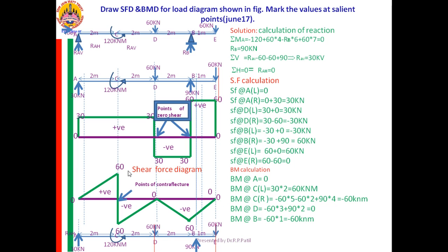So how can I define the point of contraflexure? It is a point in the bending moment diagram where SF changes its sign from positive to negative or negative to positive. That is the definition. But as for its importance, when you are designing structures in the higher semesters, you will come to know the importance of it.